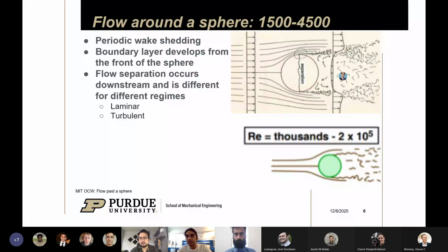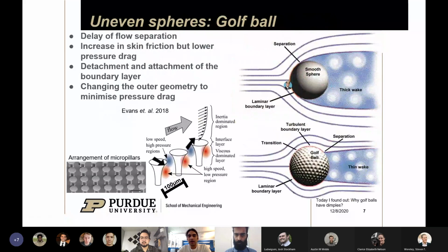In the wake region, here the velocity is plotted, and we start with a uniform velocity. However, in the wake region, we actually have negative velocity. Due to this decrease in velocity, we have a pressure drag caused in the wake region, and this acts like a suction, which pulls the ball back if, suppose, the ball is moving leftwards.